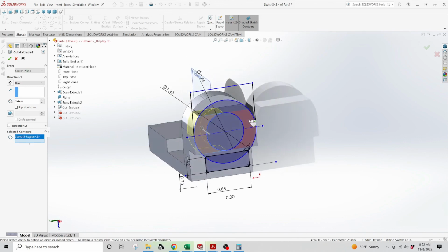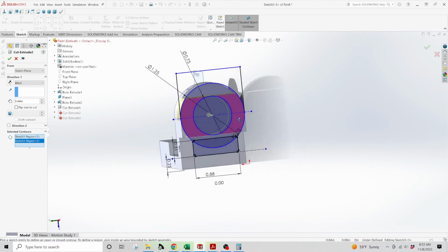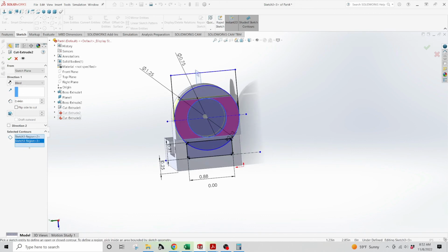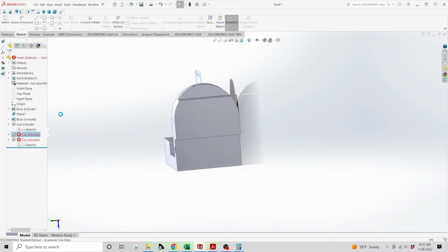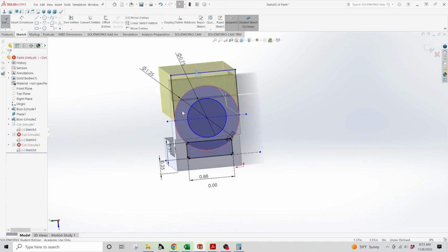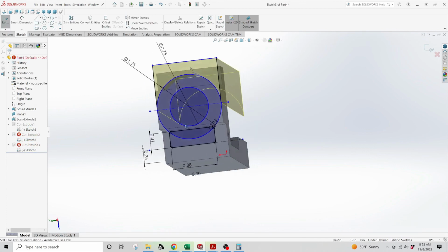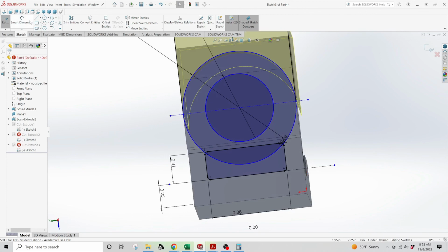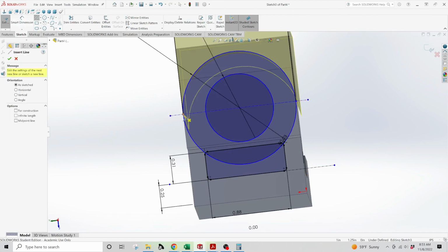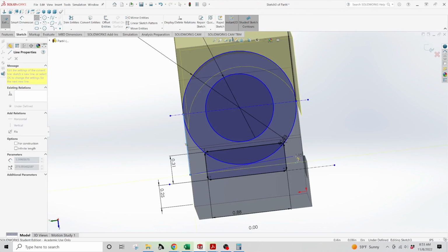Oh, and this is going to make life fun. I'm going to need to make another base rectangle down here. So let's do that. Ignore the warning errors and create the other base rectangle, because you need to be able to extrude cut as if you had a cutting die. So you guys have seen examples of this before.